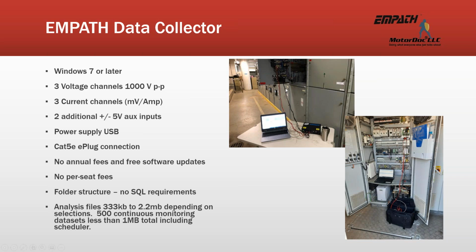So that upper left one there, that's National Institutes of Health. We're testing a 13,800 volt machine. So voltage doesn't matter as long as we can get to CTs and PTs. You do not want to connect up to, with any instrument, you don't want to connect up to anything over 1,000 volts. So this is fully capable of handling any turbine. As a matter of fact, the one that we'll cover with missing wedges, those are 12 kV machines.